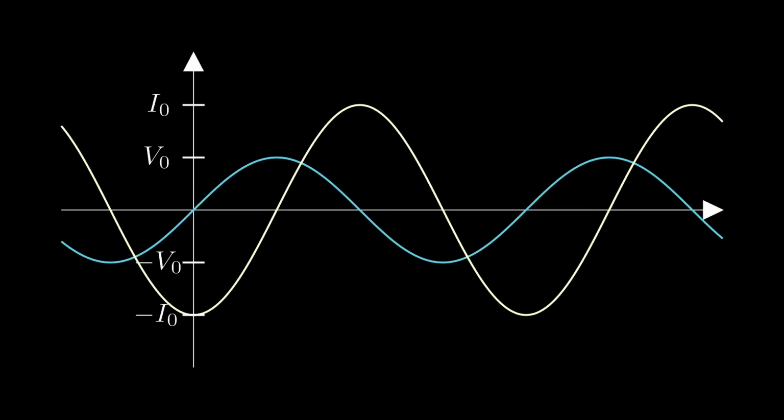in voltage. So we can shift it to the right because, remember, further to the right means further into the future. Now if we start looking at this peak right here, we can see that the voltage is at its maximum. At this point, enough voltage has been applied to get the current running through the inductor, and it'll keep running more and more as we push it more until we start pushing it in the other direction. And then the voltage in the inductor will start to slow down more and more again until we're at the peak voltage on the other side. At this point, current starts flowing in the opposite direction, and it continues to do so until we push it